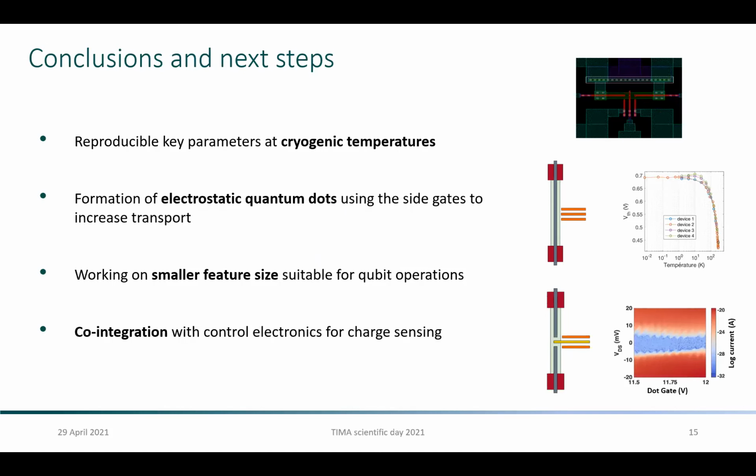So I have presented to you today that the FD-SOI technology is a promising platform for quantum computing with spin qubits, showing great promises for scale-up and co-integration. And we have demonstrated that the technology is functional at cryogenic temperatures, and that we can indeed form electrostatic quantum dots with this platform. Right now, we're working on reducing the device critical dimensions, and we're also working on the co-integration with the control blocks. Thank you very much for listening.